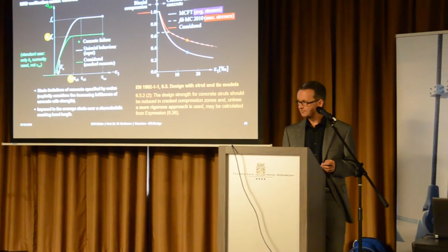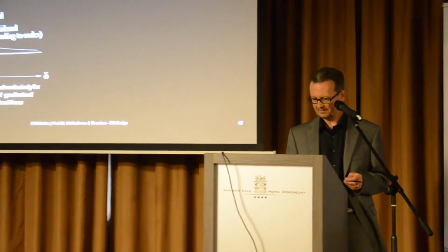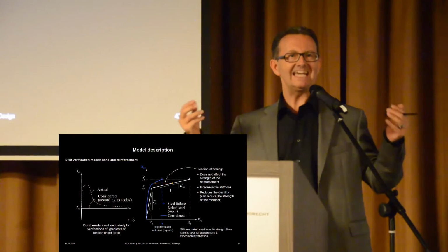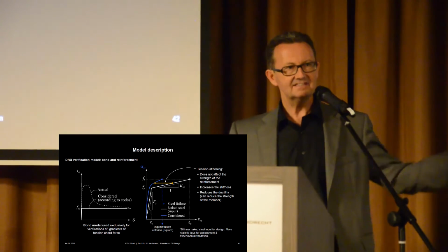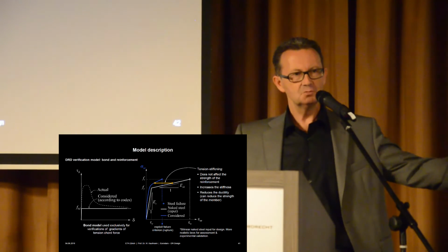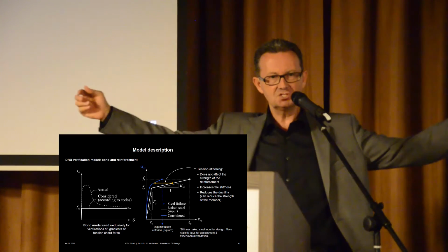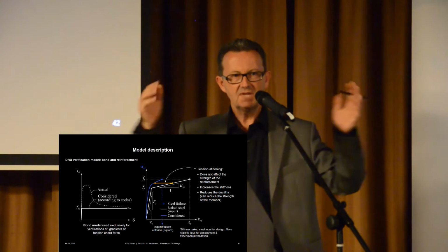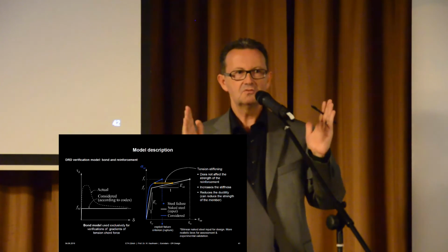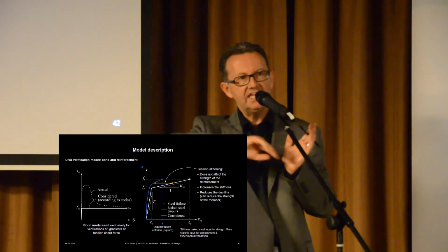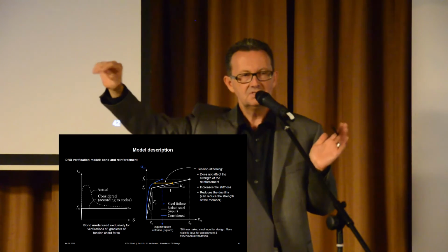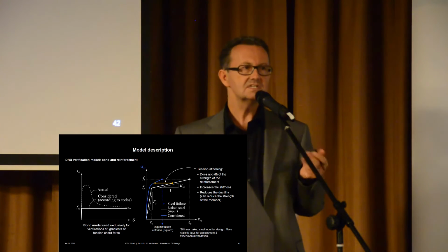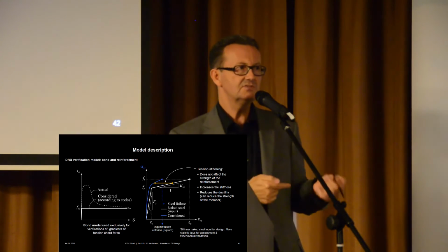Okay, so this is the curve that we are using here for the compressions. Then we need a model for bond in terms of anchorage. What I've showed before, that tension cord, implicitly I assumed that we have a constant force along that tension cord. So no problem of anchorage of the rebars, symmetric situation in each crack element. Of course, at the end of the rebars, or if we have gradients in the forces in the rebars, we don't have that situation, and we have to check this code compliant using a similar approach as for the anchorage length that we have in the codes.